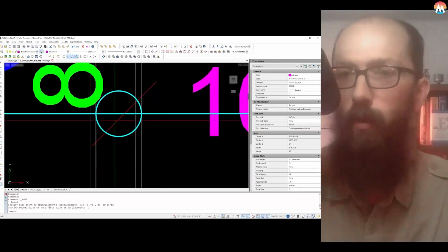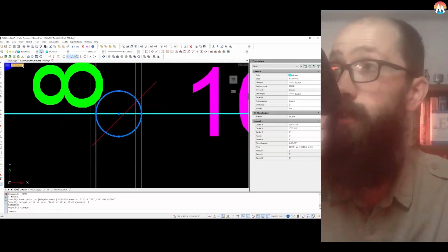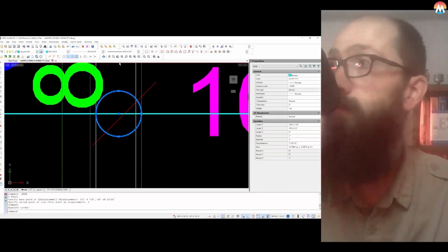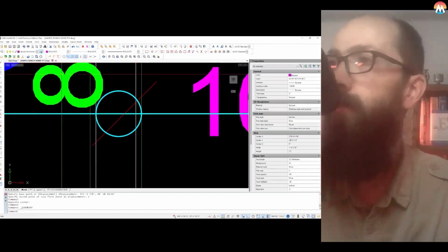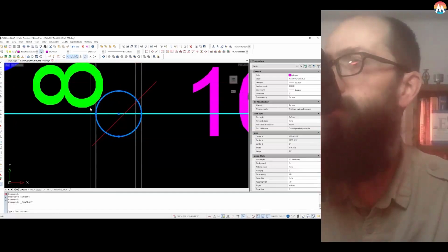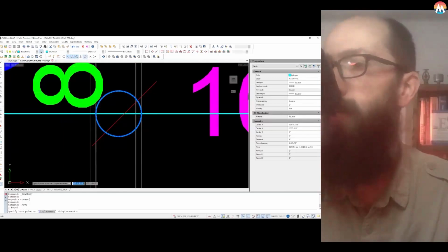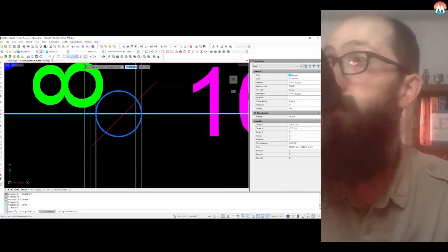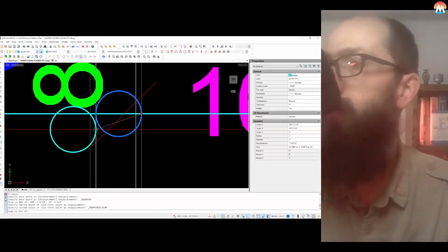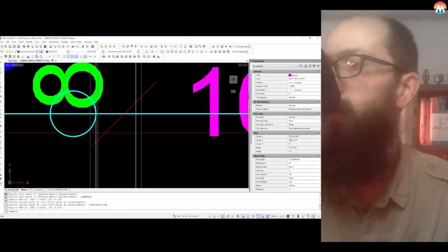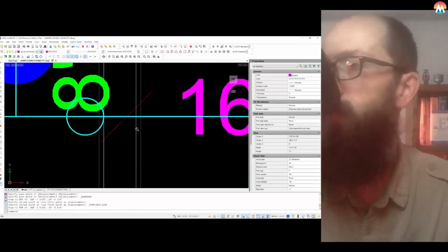This is that 2x4 wall we were talking about coming up the side of. So what I'm going to do is move this circle from the quadrant on this side. So I guess I got to select the move command. Select the circle, then move. Then it's asking me for base point of displacement. I'm going to select the quadrant, and I'm going to go to perpendicular, and I'm going to touch the wall down here. So this has got me coming up the side of that.